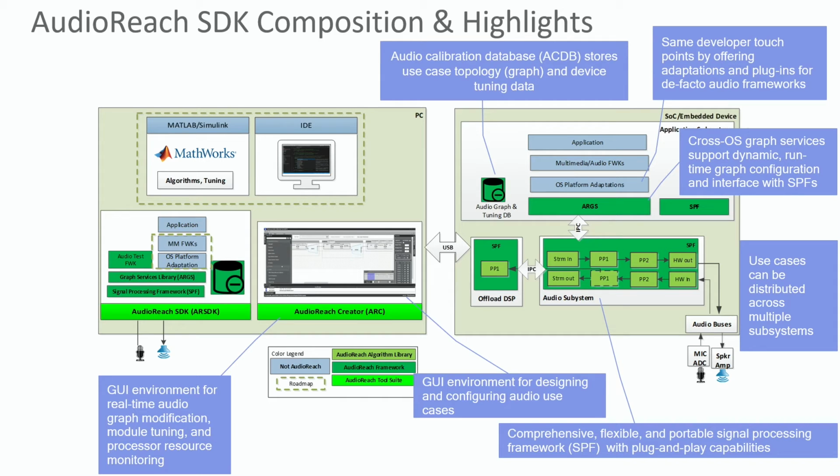It also supports module tuning, real-time tuning. So as the use case is running, you can poke the modules to change the coefficients at runtime without stopping the use case. Then it also supports processor resource monitoring. A lot of times, if you're running too much processing on the DSP, you might run out of MIPS.